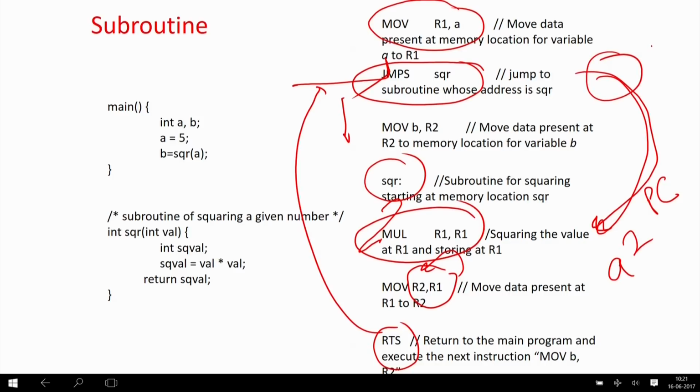Now maybe the program counter is, say, 5, so 5 is stored in a stack. Here the program counter may become 20, because we are assuming that 20 is the memory location starting address of the subroutine. So 20, 21, 22 it will go on, and whenever it reaches the return instruction, the value 5 will be popped from the stack, so that you know the program counter value is now 5, which is the place which I had left.